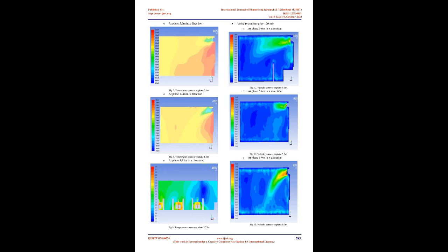It can be seen from Fig 4 that at the start humidity was around 54% to 58% and there is a large fall in humidity of air for the first 40 minutes, after which it almost becomes stable. This is due to the fact that inlet air coming from the air conditioner is dry. So such a low level of humidity can cause discomfort for humans.